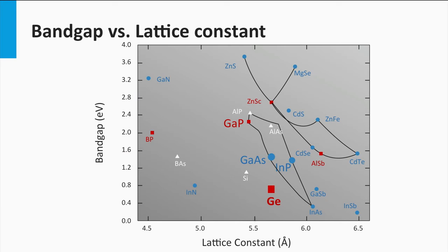Let's look again at the phase diagram of semiconductors, where the band gap is plotted versus the lattice constant. The triple junction is processed on a p-type germanium substrate. The bottom cell is a germanium cell. On top of this, you would like to place a junction that has, first, the same lattice constant and, secondly, a higher band gap. As you can see, gallium arsenide has exactly the same lattice constant as germanium. This means gallium arsenide and germanium can make good interfaces without any coordination defects related to mismatched lattices.